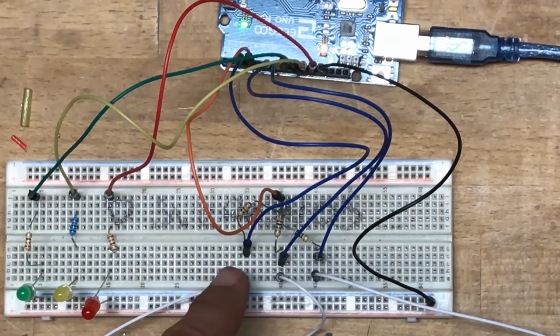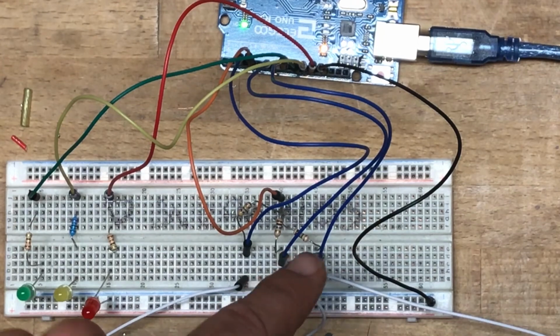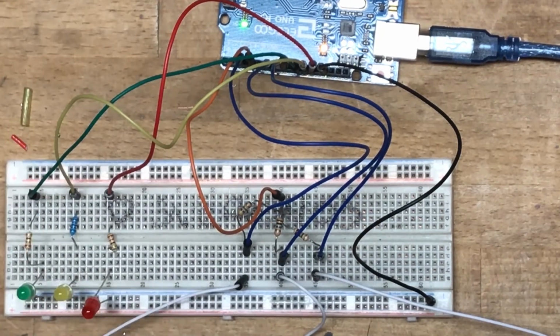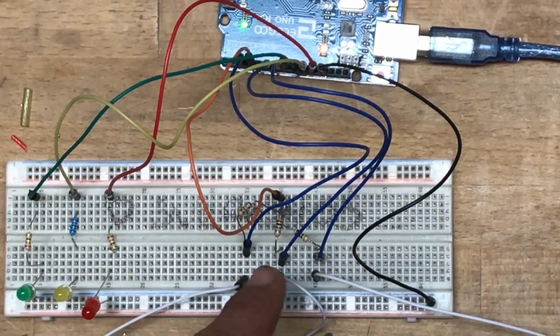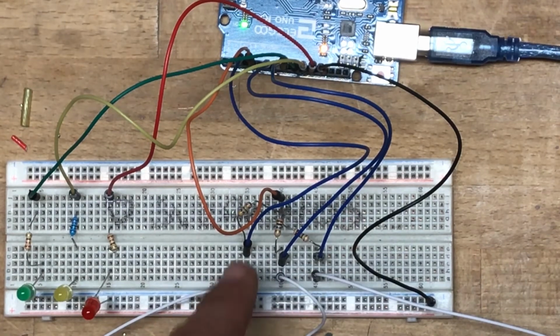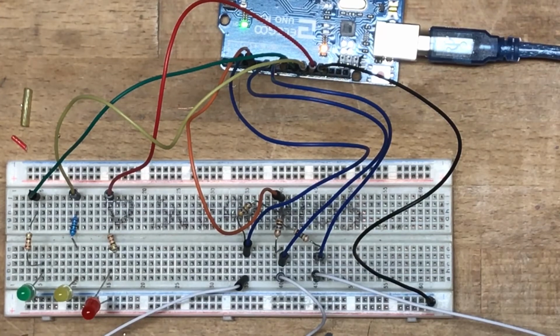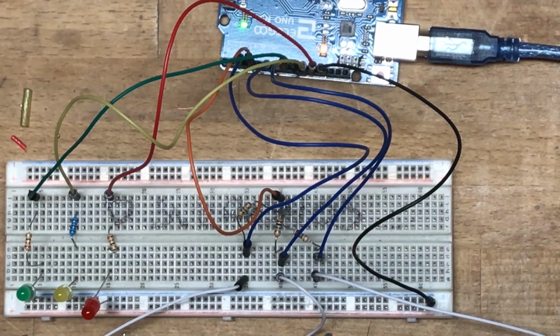The other end is each connected to that blue jumper wire. It goes back to pins 2, 6, and 8, respectively. That's connected with the white wires to our pieces of foil, our tools, whatever metal conductive objects we have. The bigger that object, the larger of a range of an area you can actually start to sense through. So we'll take a look at the code and a little bit more at the circuit in just a second.